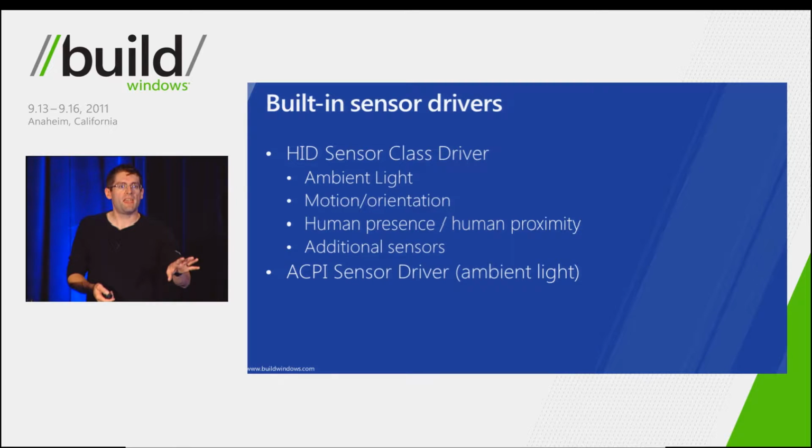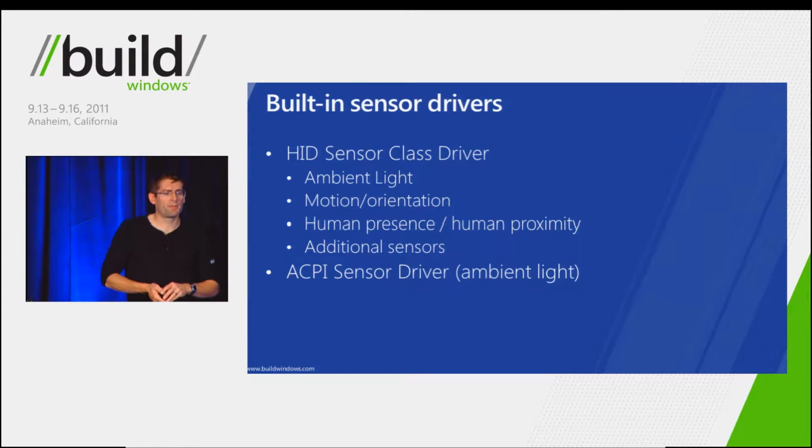We've also got the ACPI ambient light sensor, which provides sort of a legacy approach to connecting ambient light sensors. This is really most relevant on x86 and x64 platforms, and it allows more flexibility under the covers with regard to how the ambient light sensor is hooked up. And again, you have no driver work to do if you're using that driver.